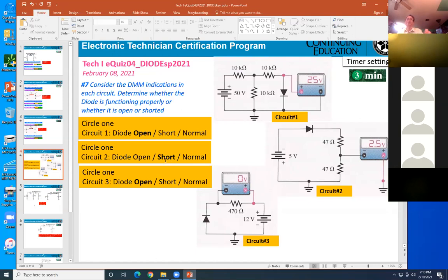But wait, there's a positive voltage on the cathode, which means that you replace the diode. Don't analyze the circuitry, go based on the meter. The meter measures 2.5. How come they get 2.5? Because the diode is shorted. Yeah, that's what they want you to answer. I see what you're saying now, Mr. Pham. The object of this particular circuit is to figure out why you get 2.5 volts there.